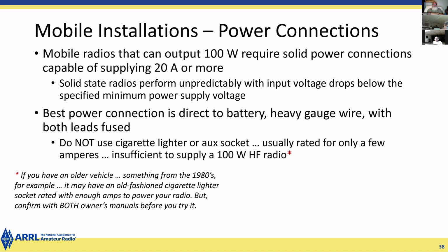I will say also that most car electrical systems are designed for two things: one, to supply a huge amount of current when you're cranking the engine, 100 amperes or more, for a few seconds, and then while you're driving the car, to supply enough power to both recharge the battery up to its full charge and operate all the electronics in the car, plus any motors, for instance in your air conditioning, if that's not run off the engine itself.